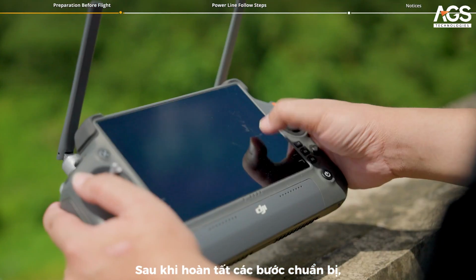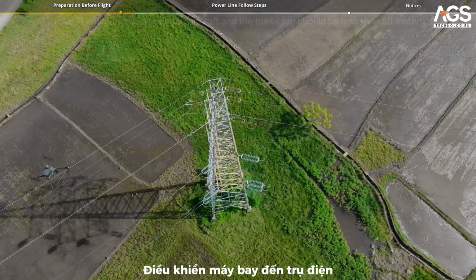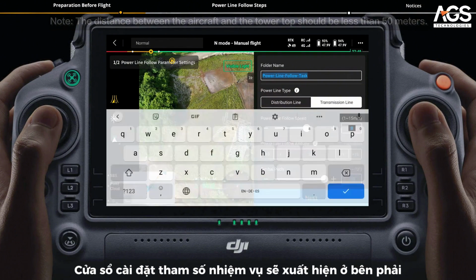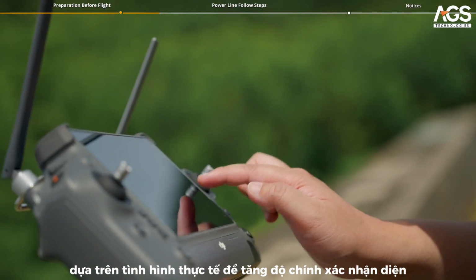After all the preparations have been completed, toggle the flight mode switch on the remote controller to N mode. Control the aircraft to fly above the electric tower. Tap the power line follow icon, and the task parameter settings window will pop up on the right. Edit folder name. Select a corresponding power line type based on the actual operating situation.